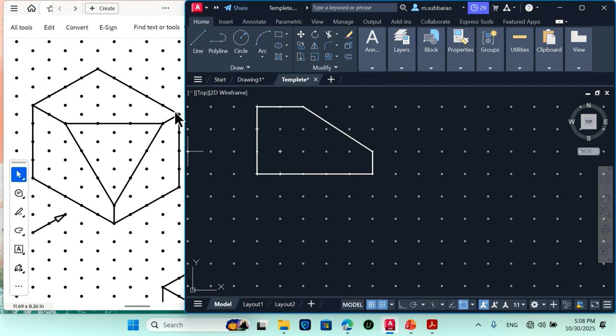So this line I will first draw. I will draw this line, and 10 mm I will draw this side. Again 40 mm down, and again 20 mm this side. So this line is joining from this corner point to this point. So again you will be joining these two lines. So this becomes the top view of this diagram.